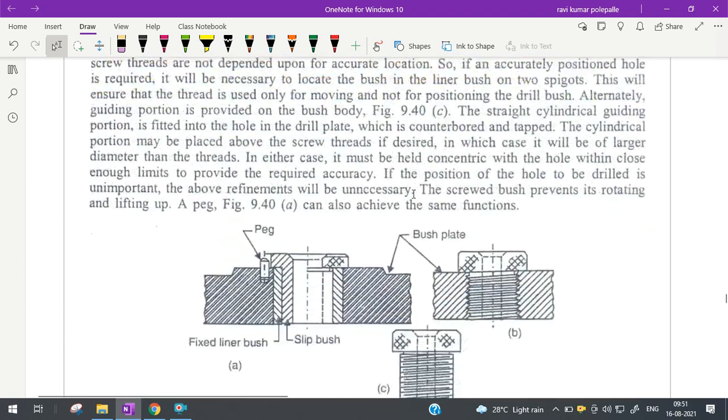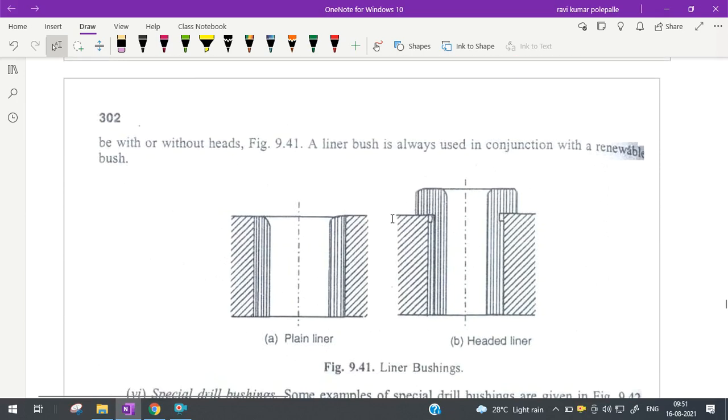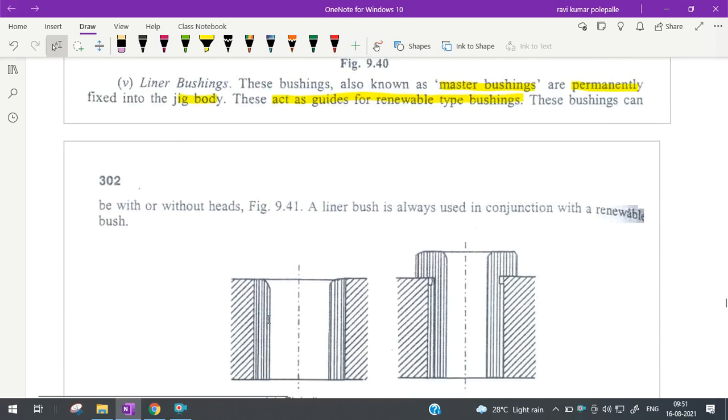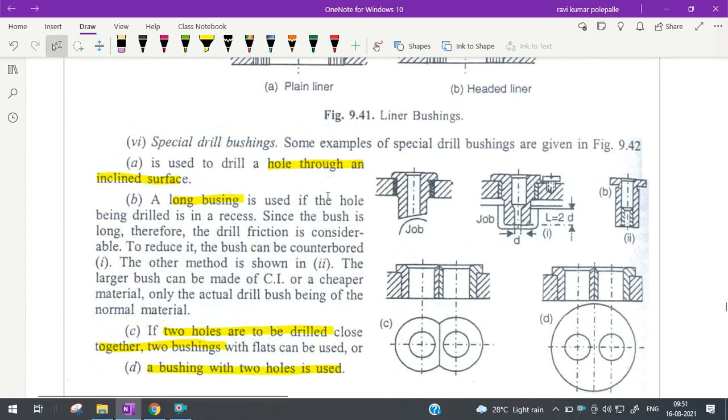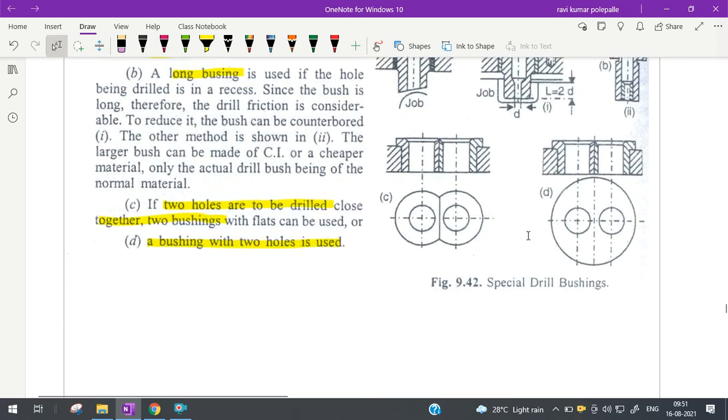It is simply a plate. It is almost the same as the type of job which we wanted to actually make. This simple plate, which we call a drill plate or template, is put on the workpiece and the drilling is carried out. You may notice that even bushes shall not be provided. The plate itself should have holes which should be hardened.